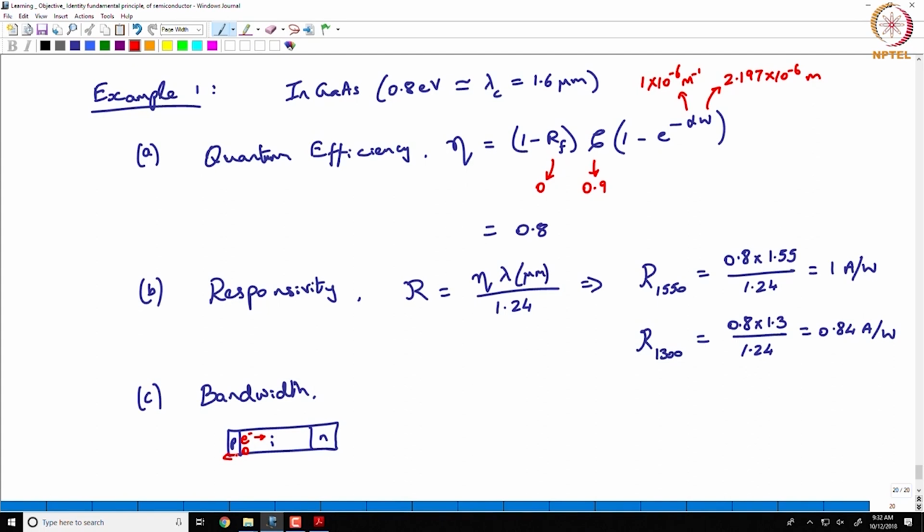It will not be like an instantaneous response, it will be a response that is delayed by the longest delay that you are going to see, corresponding to the case where the electron is going to have to traverse that entire structure, right. So, that transit time will be one limitation.